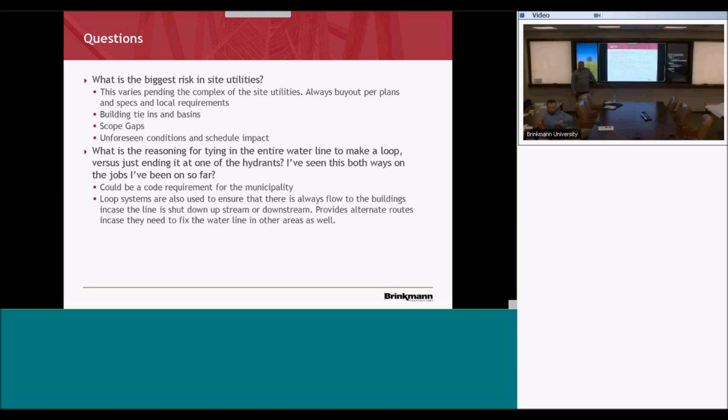They wanted us to build these hot boxes, is what they called it, over the top of each one of the backflow preventers. Then you had to run power and everything out to each one. So we looked at it a bunch, priced some different options, and talked to the city. We ended up being able to come into the building, hit the backflow preventer there, and after the backflow preventer, we teed off and went back outside and then hit all of the fire hydrants.